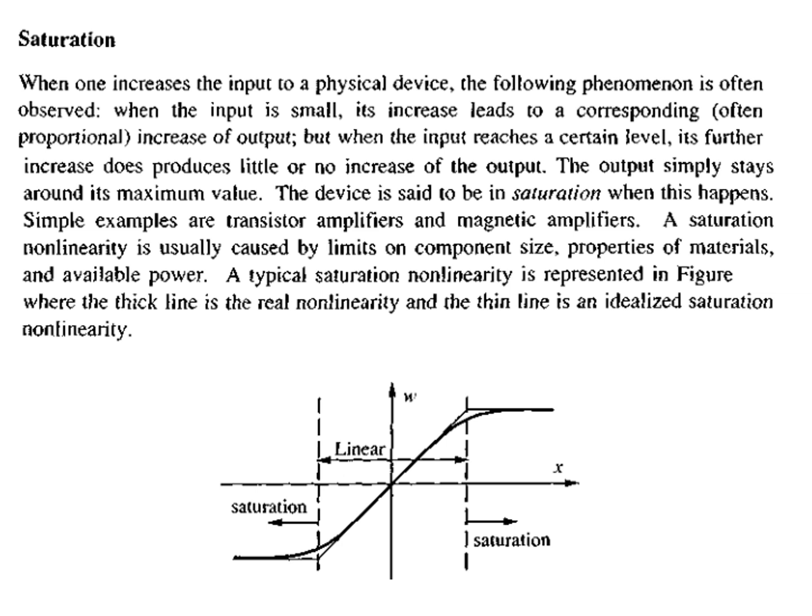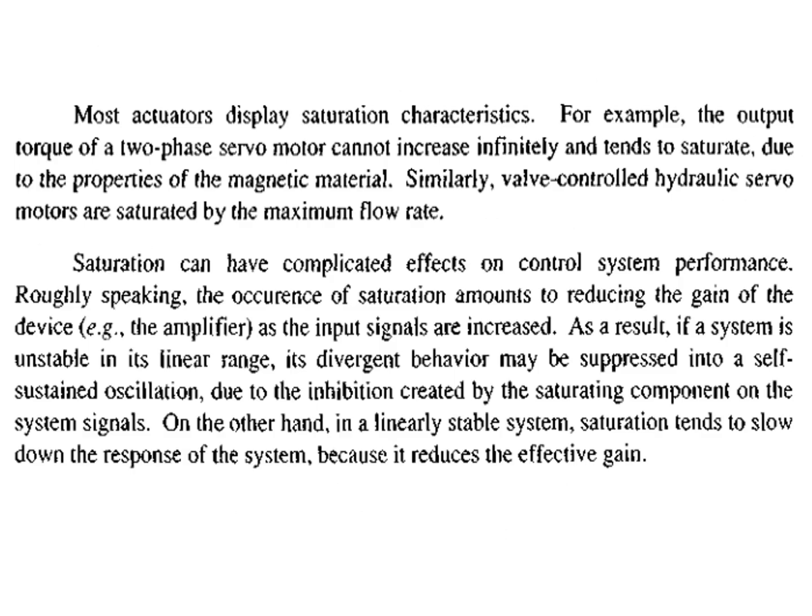Okay, when one increases the input to a physical device, the following phenomenon is observed. When the input is small, an increase leads to a corresponding increase in the output. But when the input reaches a certain level, a further increase produces little or no increase in the output. The output simply stays around its maximum value. This is called saturation. This type of saturation also can lead to instability. Another example is the output torque of a two-phase servo motor, which cannot increase infinitely and tends to saturate due to the property of the magnetic material. This is another example representing the saturation characteristics.